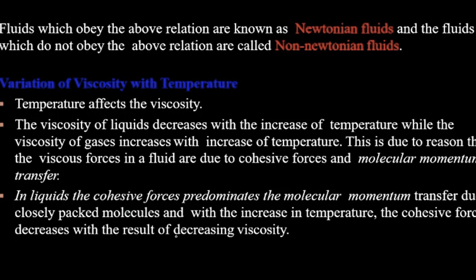This is due to the reason that the viscous forces in a fluid are due to cohesive forces and molecular momentum transfer. In liquids the cohesive force is higher. In liquid, the cohesive force predominates over the molecular momentum transfer due to closely packed molecules. With the increase in temperature, the cohesive force decreases, with the result of decreasing viscosity. When there is no cohesive force, there is no question of shear strain, and viscosity will not be there.